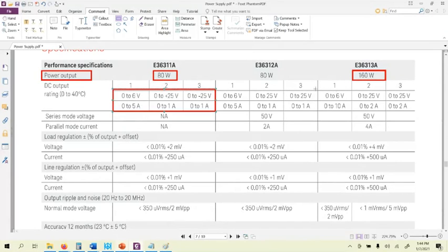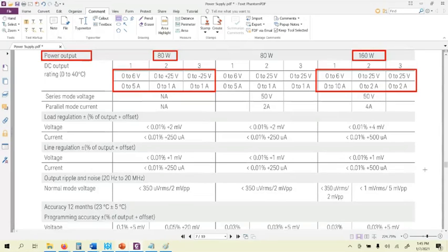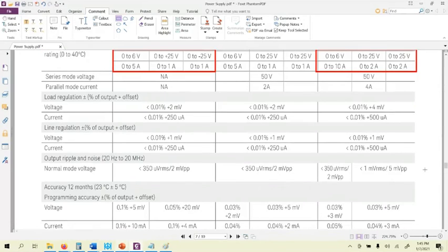Similarly, you can do the calculation here also. So it is not just a small 80 watt power supply, but you have to understand where it is actually delivering you that power. So when you are going to purchase a power supply, remember this kind of stuff. You have to go and understand these things. How many of you remember this particular term? Load regulation. And see what it means here. Anyone who remembers what load regulation is?